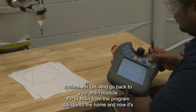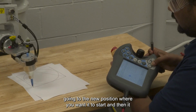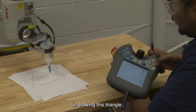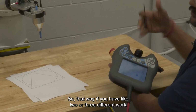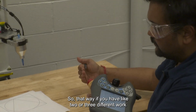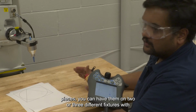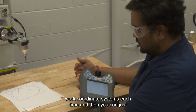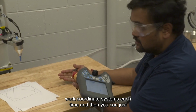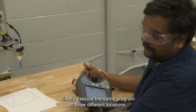Going to the home, and now it is going to the new position where you want it to start, and then it is drawing this triangle. So, that way if you have like 2 or 3 different work pieces, you can have them on 2 or 3 different fixtures. With the same program, you can just define those 3 different work coordinate systems each time, and then you can simply execute the same program at 3 different locations.